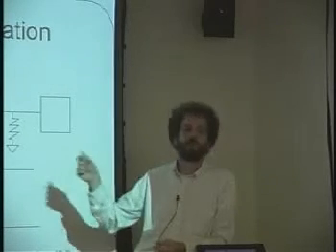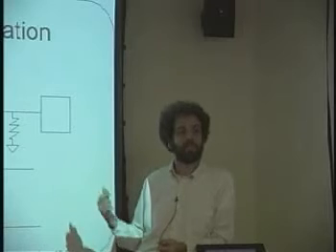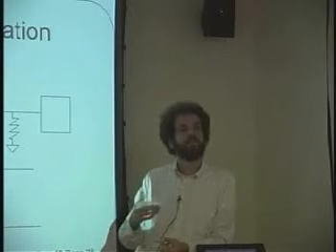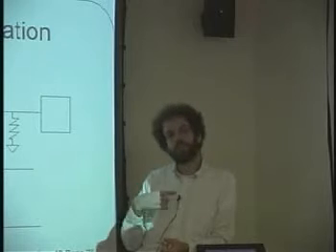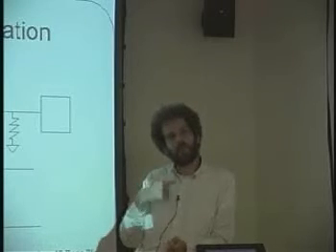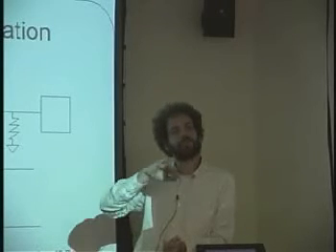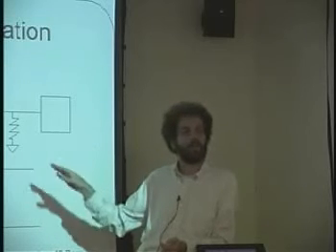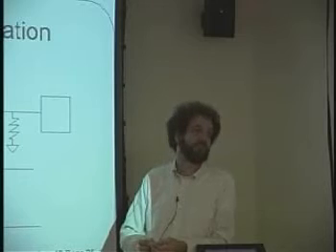If I want to run a computer slowly, without terminators, all I need to do is change between 0 and 1 very slowly. The echoes still happen, but they happen in a time that's short compared to the time of the transitions between zeros and ones. So if I don't want to send signals too rapidly in the system, the need for terminators is much less.